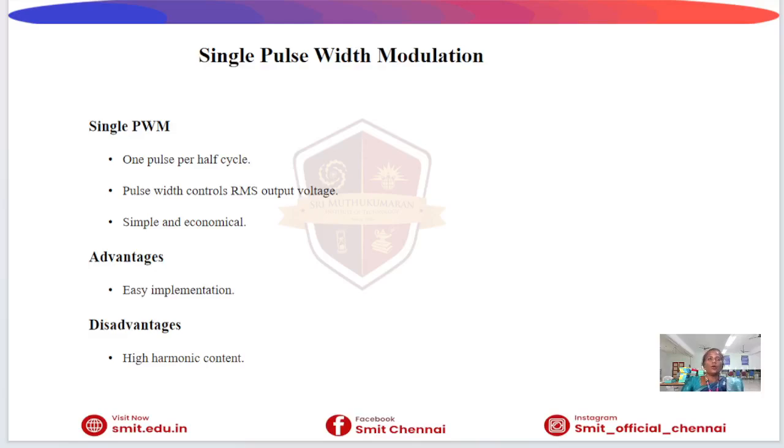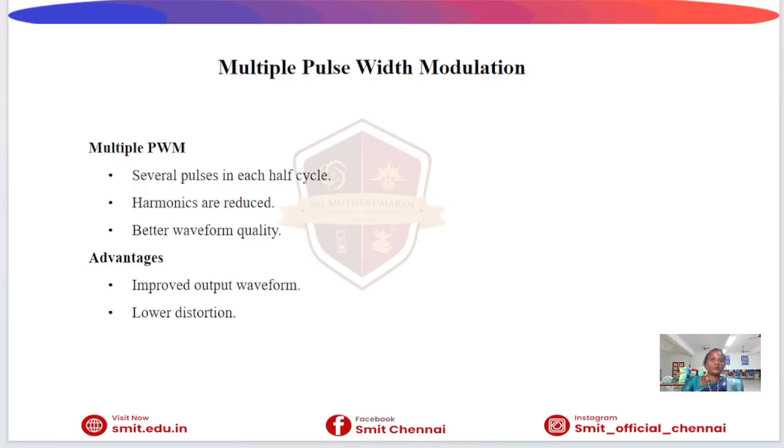However, the major drawback is that the output waveform contains a significant amount of harmonics. Because of this limitation, single pulse width modulation is generally used only in low power or less demanding applications where waveform quality is not a major concern.